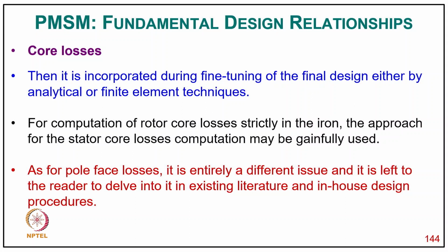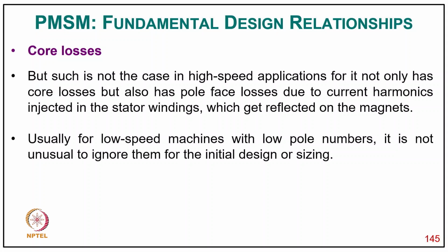either by analytical or finite element analysis technique, and for computation of rotor core loss strictly in the iron, the approach for the stator core loss computation may be gainfully used. As for the pole face losses, it is an entirely different issue, and it is left to the reader to dwell into in existing literature and in-house design procedure. But such is not the case in high-speed applications, for there it not only has the core losses but also has the pole face losses due to the current harmonics injected into the stator winding which get reflected on the magnet.